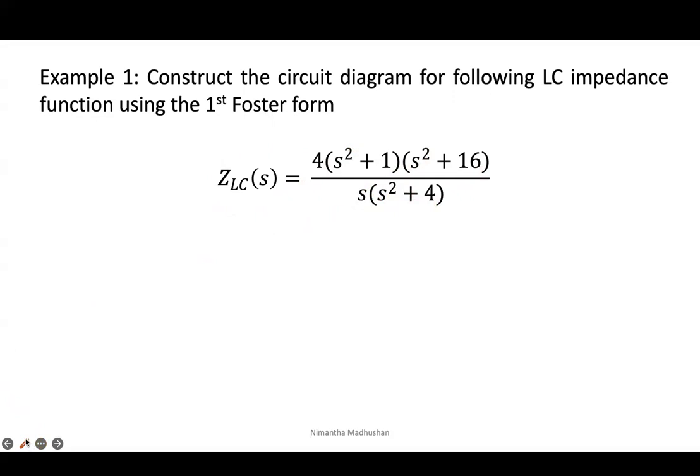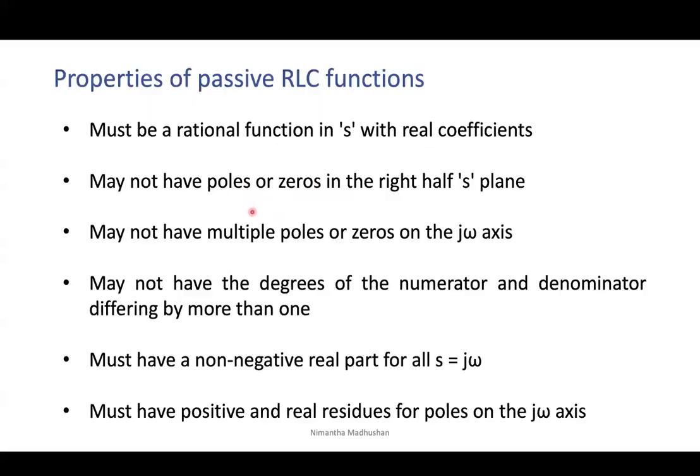Before constructing the circuit, we have to check whether this function is realizable for synthesis, to develop a network. To verify realizability, there are some properties. These are the general properties for passive RLC functions.